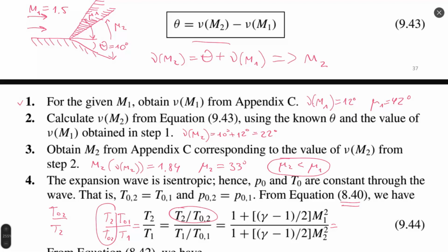No, it's already reversed here, as we might see. So temperature 2 and Mach 1 are on the opposite part of the ratio. We know that this temperature ratio should decrease, so it should be smaller than 1 because temperature drops.